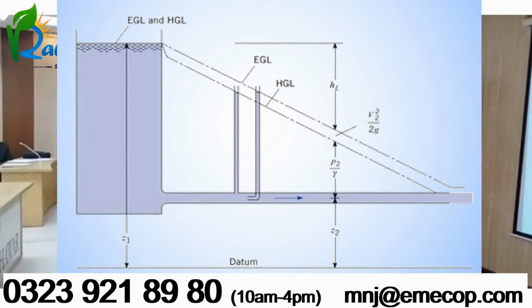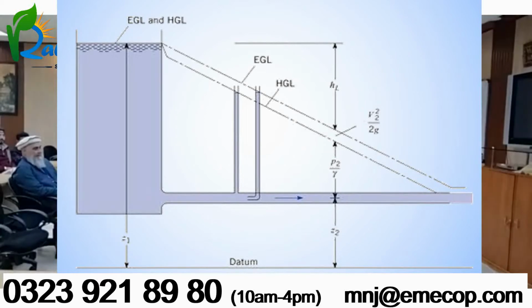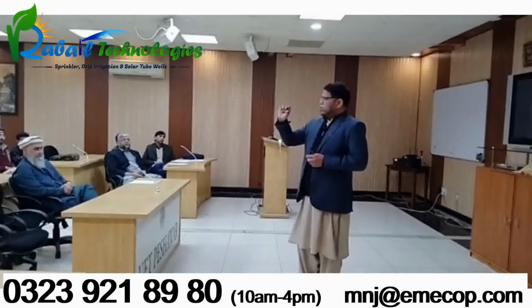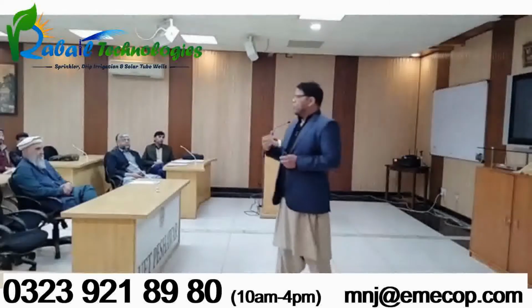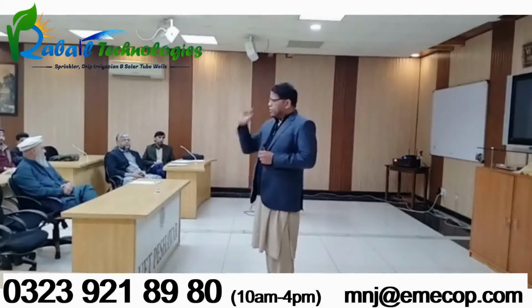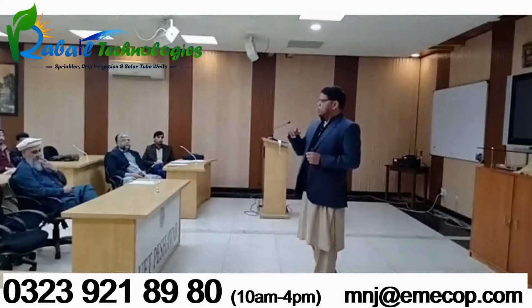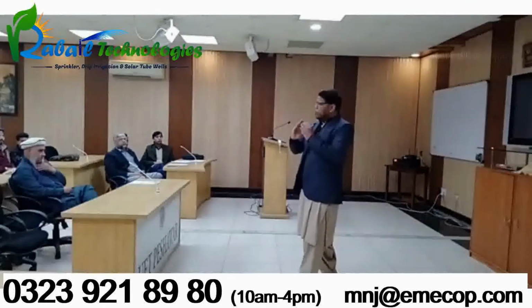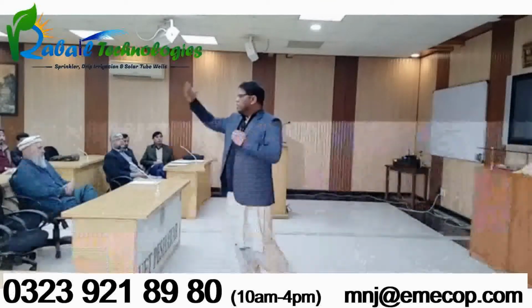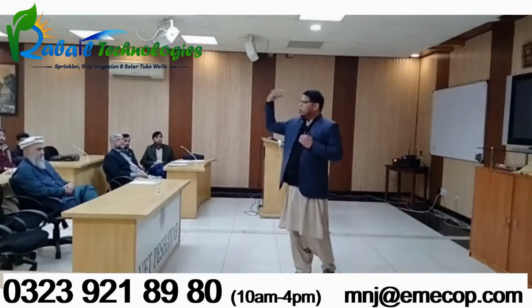For example, if you are familiar with rain guns or sprinklers, what we are doing is that up to the nozzle, we want to increase the hydrostatic pressure and reduce the velocity head. But immediately at the entrance of the nozzle, what we want the nozzle to do is to increase the velocity head. Because with the velocity head, the water now has to travel from the nozzle up to some other point like 100 feet, 50 feet, 150 feet, or even 170 and even 200 feet.